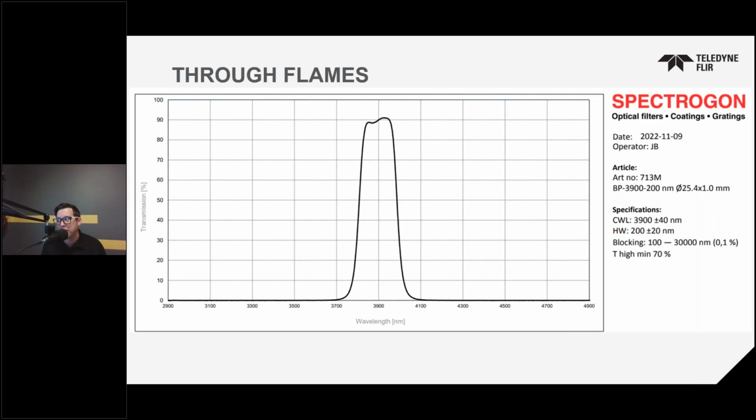We have camera systems that leverage custom cold filtered detectors for that purpose-built ease of use, for somebody looking in a furnace or something like that regularly, as well as flexible systems that leverage warm filters placed behind the lens or in a filter wheel. That's where you'd see more on the science and research side, where someone has a specific application, some requirement where, let's say, they want to see how a material reacts within a flame. Maybe it's a munition, maybe it's some energetic, maybe it's a piece of steel, and they just want to be able to see through the flame to see how the material reacts, and they don't want it forever that way.